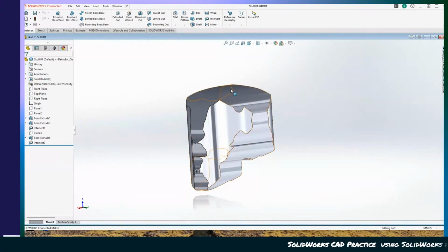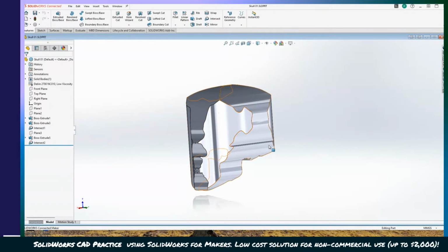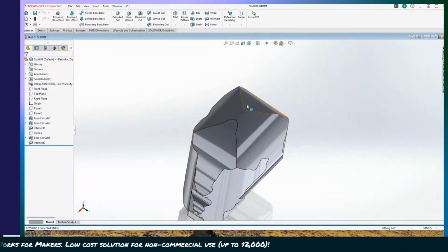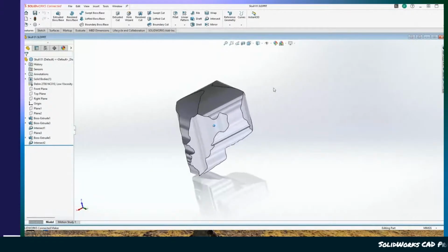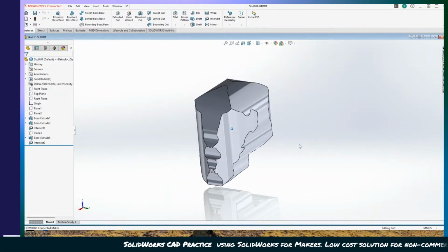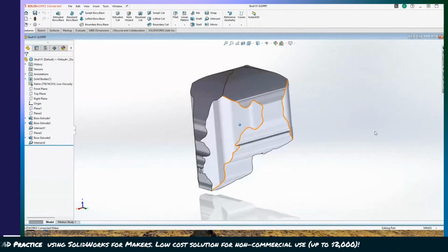So I'm going to try creating some incremental planes along here and see if I can sketch on each plane to follow these contours but make it more shaped well, so it looks more like an actual skeleton. So we'll see how it goes.